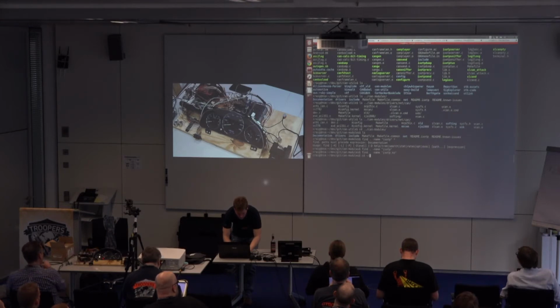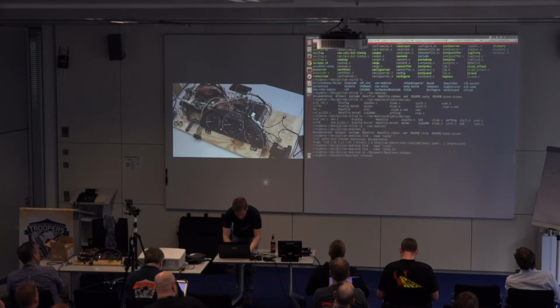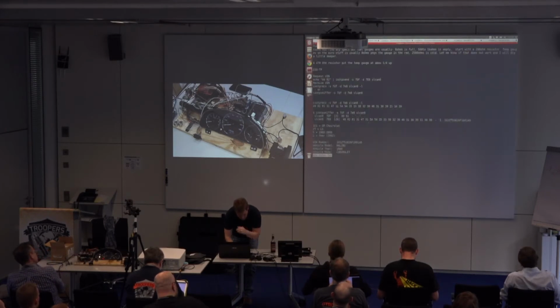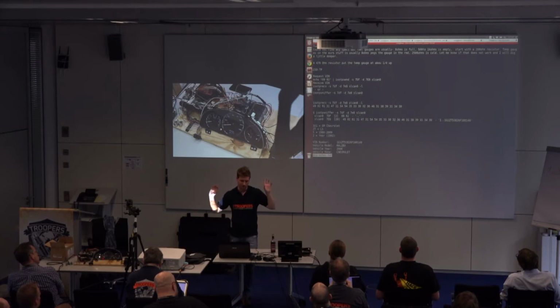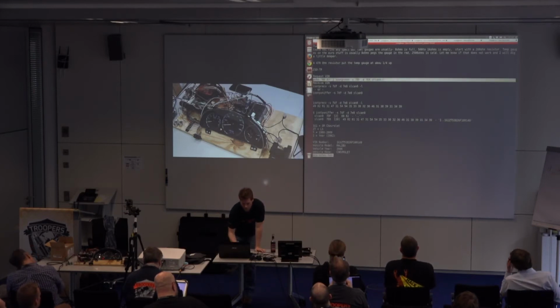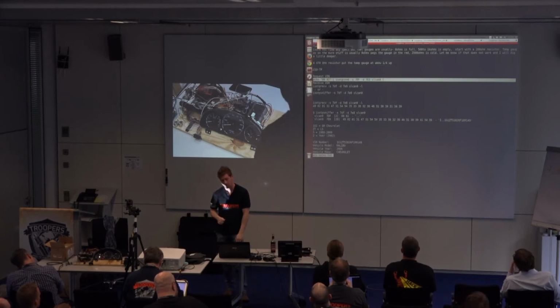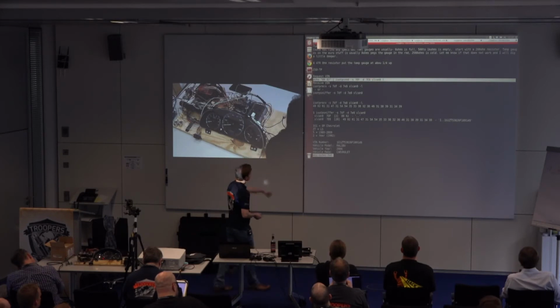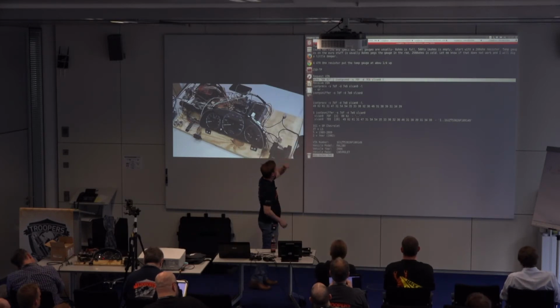It'd be under documents. The thing that's tricky about it is you have to have basically two terminal windows open. What I'm doing here is the command to request it on the command line, and you're using isotp send, 7DF and 7E8.